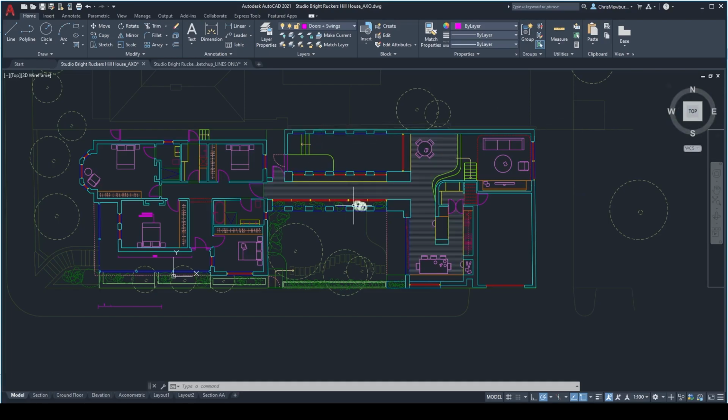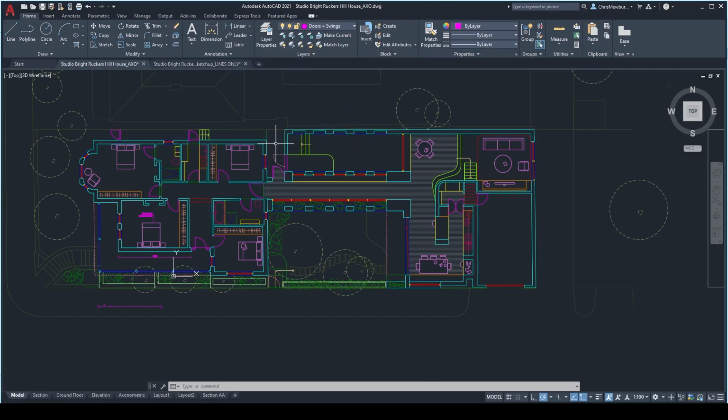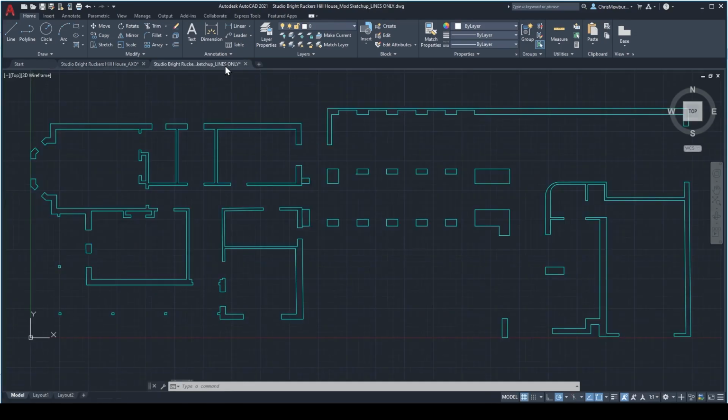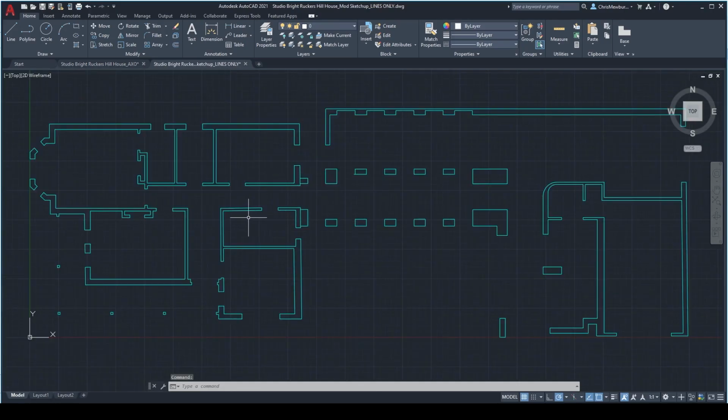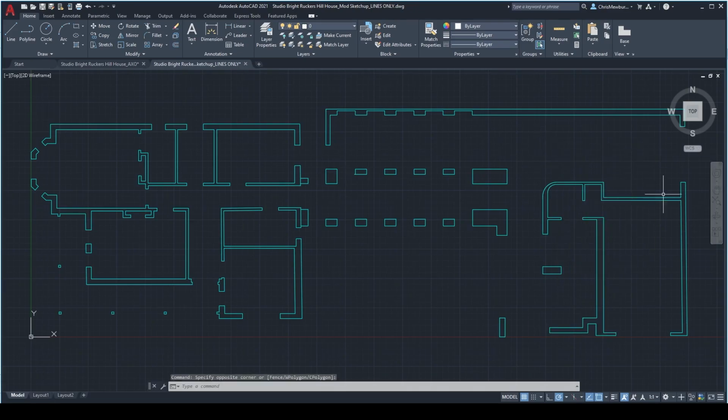And so what you can do is, of course, turn off the walls layer, delete everything, and then turn the walls layer back on. Very, very simple, very, very straightforward. So again, turn your walls layer off because that should all just be on one layer by itself. Delete everything, turn your walls layer back on, and then you should have something like this. Now, typically what I would do is go back through and also delete all of the layers as well, because sometimes depending on how you import it, the layers can come through into SketchUp too, which can make things a little bit more complicated for you. So you can delete all the layers as well. But for now, this is fine.